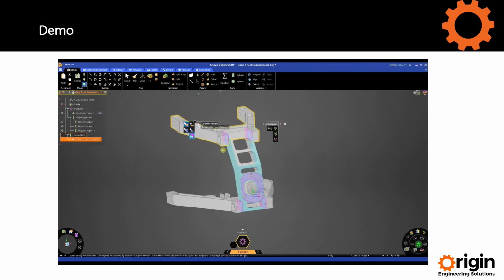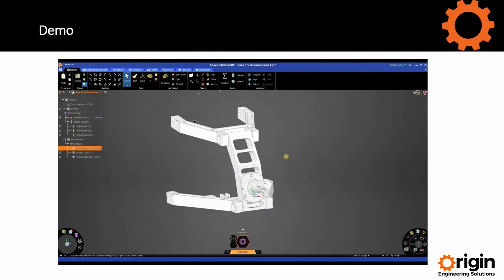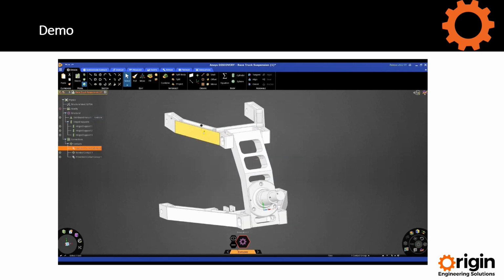I don't want all these to be bonded, and these are at the moment bonded, so I might not want all these to be bonded. So I'm going to set this one here first to permanently bonded, as I want that to be that. These other 2 I'm going to actually exclude from contact detection. So I'm going to use this tool here, and they're going to be excluded from contact detection because I want to create my own contacts.